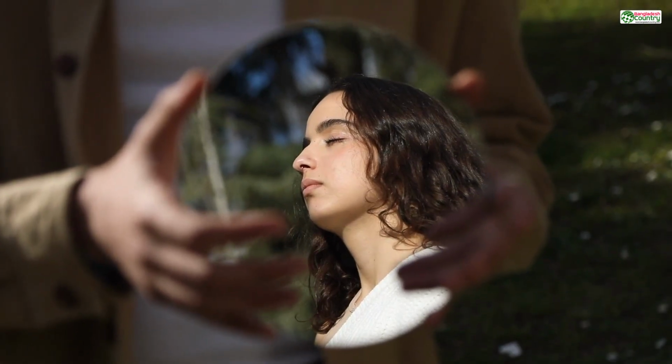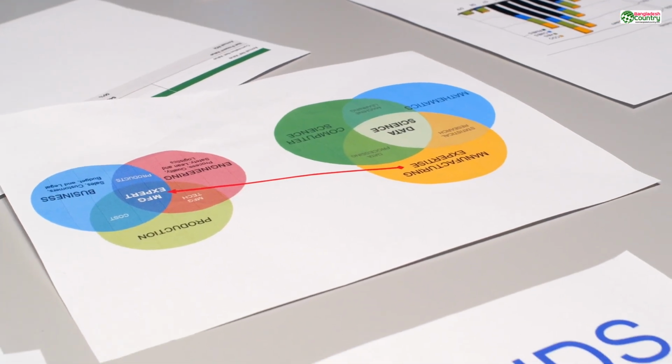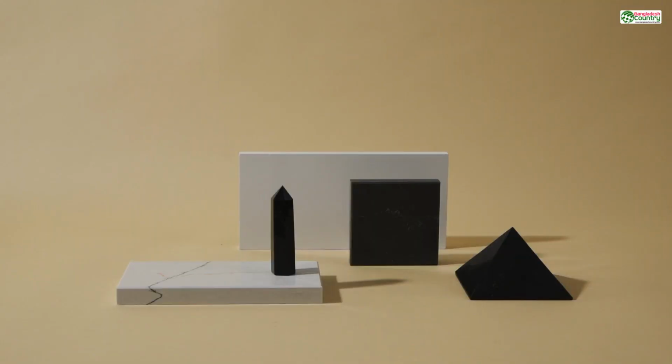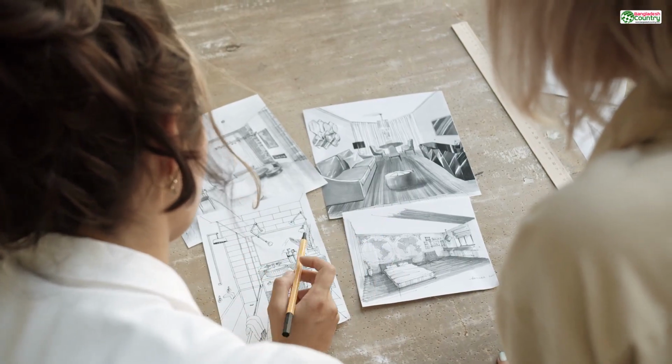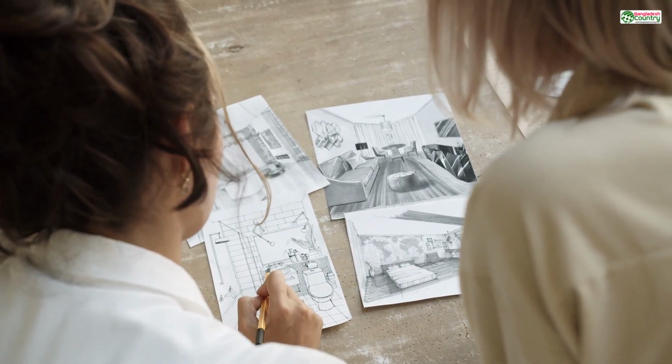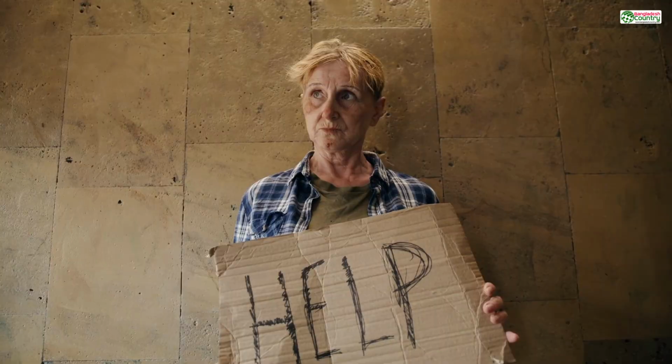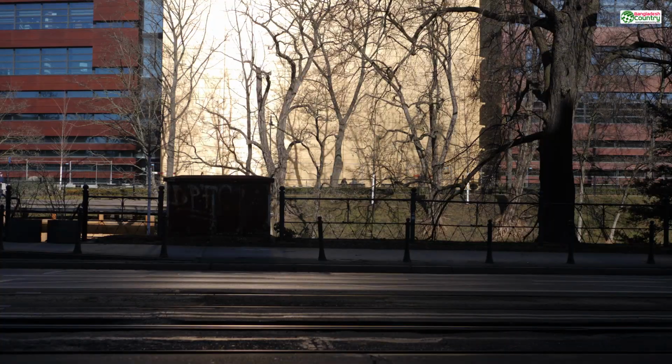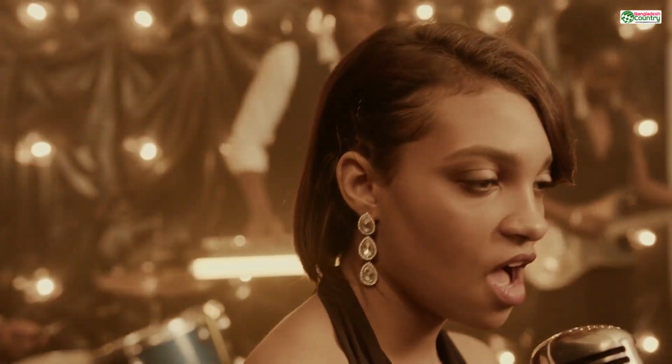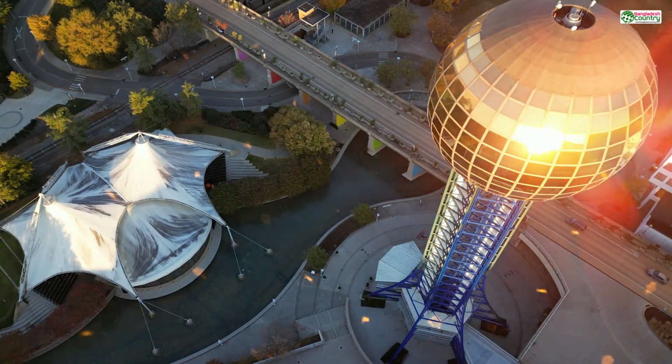It's also about physical reality. A solid object is heavy. If you're designing a part for a drone, a piece of cosplay armor, or anything that needs to be lightweight, hollowing is non-negotiable. You get the same external dimensions, the same look, but a fraction of the weight. And here's the reason that trips up even intermediate users, especially in the world of resin printing. Hollowing is crucial for the success of the print itself.